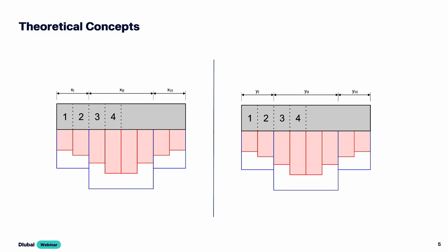And to capture this behavior accurately, RFEM divides each reinforcement direction into 8 design strips, 4 strips on each side of the column. And because the system is symmetrical, it is also sufficient to consider only one half with strips 1 to 4 here, for example. Strip 4 is located directly below the column, while strip 1 is located at the foundation edge.